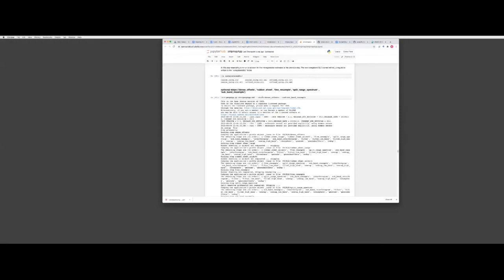In that case, what we call rubber sheeting is needed. You need to turn these options on, which are off by default, and do rubber sheeting, which means doing cross-correlation again, and this time not asking for only a constant over the entire image, but for an image of the offset derived from the cross-correlation.